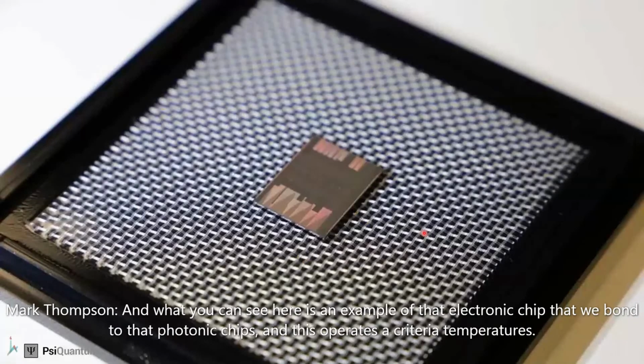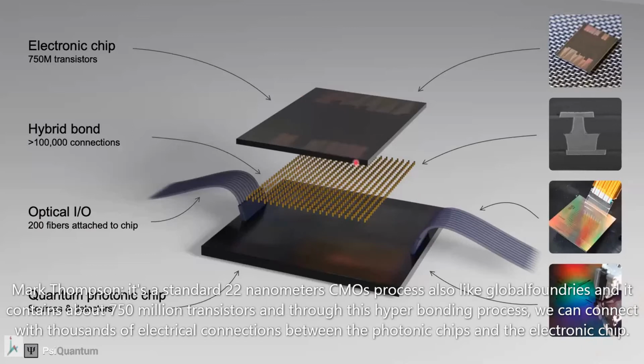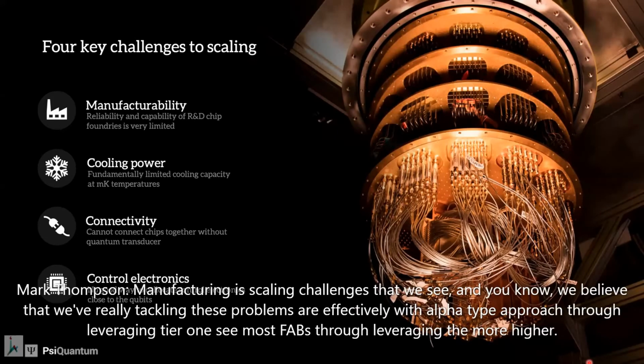And what you can see here is an example of that electronic chip that we bond to that photonic chip. So this operates at cryogenic temperatures. It's a standard 22 nanometer CMOS process, also at GlobalFoundries, and it contains about 750 million transistors. And through this hybrid bonding process, we can connect with thousands of electrical connections between the photonic chip and the electronic chip. So in terms of the challenges to scaling that we see, manufacturability, cooling power, connectivity, and control electronics are the key manufacturing scaling challenges that we see.